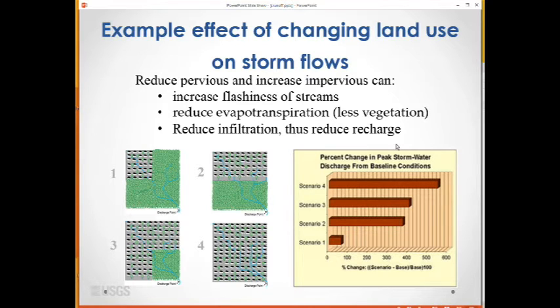As development increases, peak stormwater discharge increases. However, the increase in stormwater flow may be nonlinear. Part of the nonlinearity is related to reduced soil infiltration and plant transpiration as development increases. Users could develop simulations using different values of impervious fractions to estimate changes in stormwater flow.